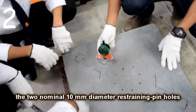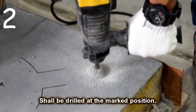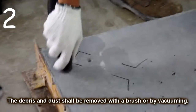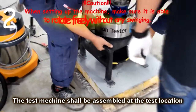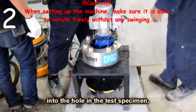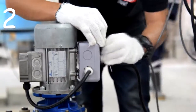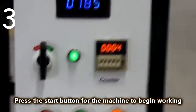The 2 nominal 10 mm diameter retaining pin holes shall be drilled at the marked position. The debris and the dust shall be removed with the brush or by vacuum. The test machine shall be assembled at the test location, and the retaining pin shall be inserted through the feed into the hole in the test specimen. It shall be checked that the abrasion head is free to rotate or not. Press the start button for the machine to begin working.